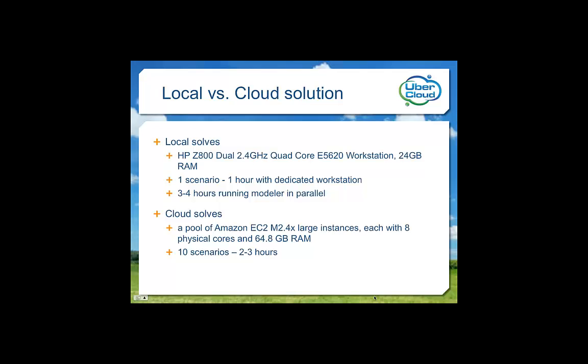So to recap, local solves were performed on an HP Z800 and could take as long as 3 to 4 hours when the machine was busy working on stuff. The cloud solves were run at one of the Autodesk HPC centers, with results from 10 scenarios returned in under 3 hours. With order of magnitude savings recorded and even greater savings hinted as procedures for virtual valve testing are refined, SimCFD has proven to be a valuable tool in this design engineer's toolbox.